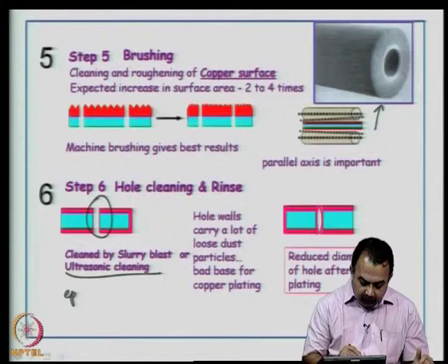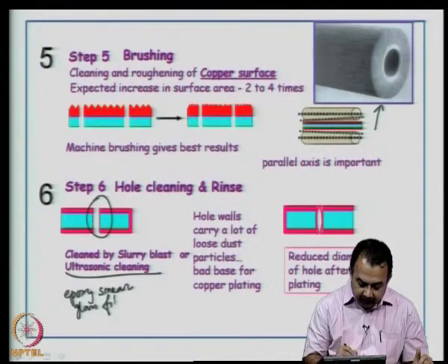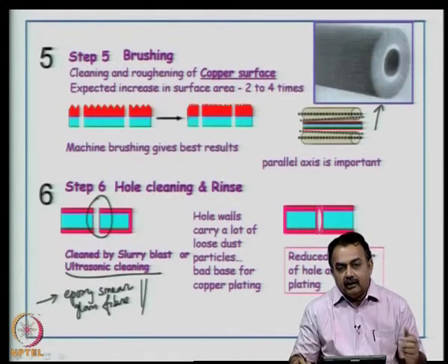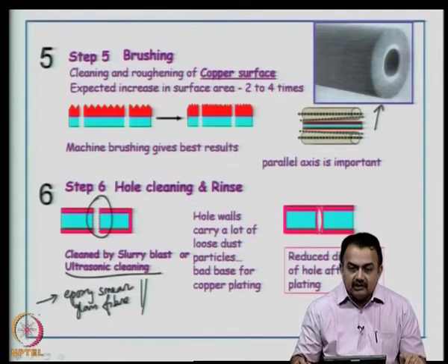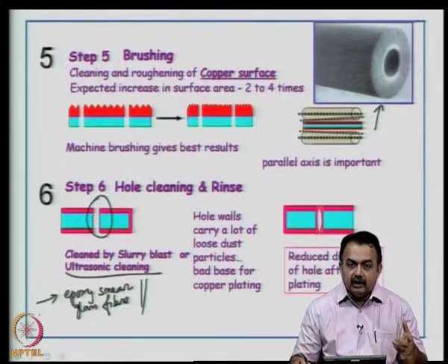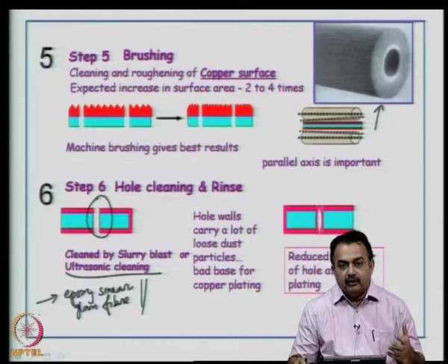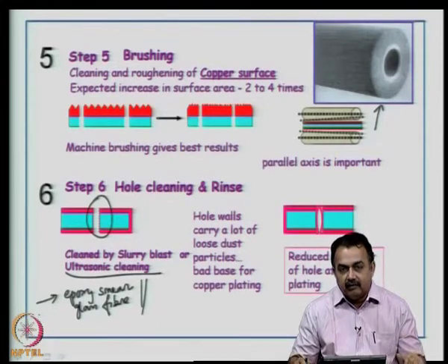So, what you will basically see is, after drilling, an epoxy smear or a glass fiber which has to be removed. Smear is basically coming from the melting of the resin during the drilling process and a quick solidification. They can also carry a lot of loose dust particles that come from the drilling.